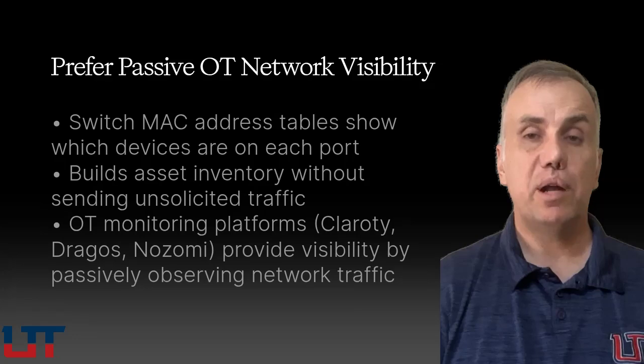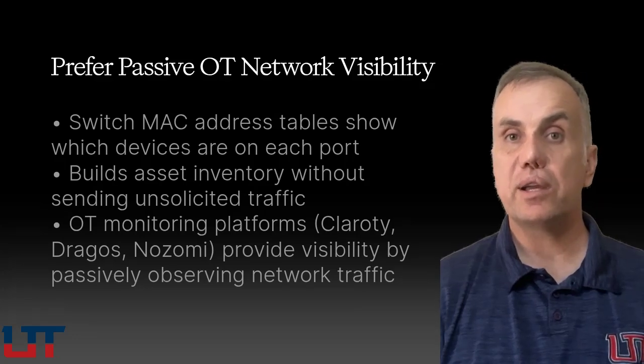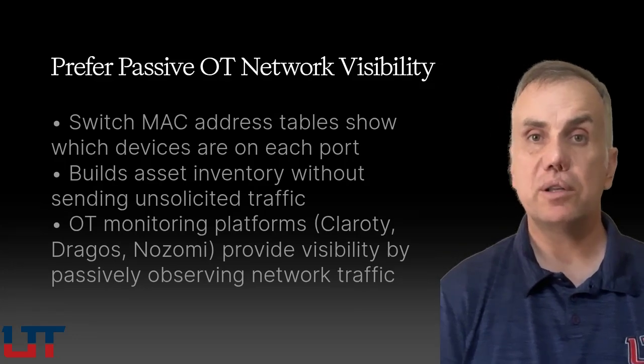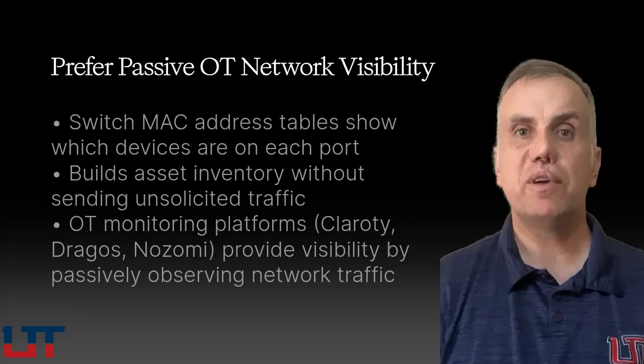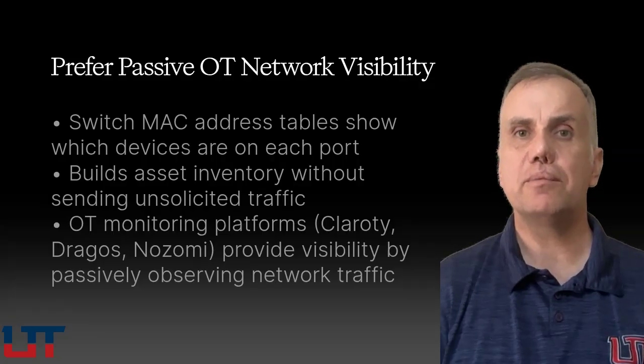Dedicated OT network monitoring platforms like Claroty, Dragos platform, and Nozomi Networks Guardian are designed specifically to provide network visibility in OT environments without active scanning. They work by passively observing the traffic that's already on the network. They see every communication, every device, every protocol, and every connection without generating a single packet of their own. We'll cover these tools in more detail in the next video.